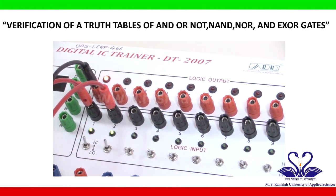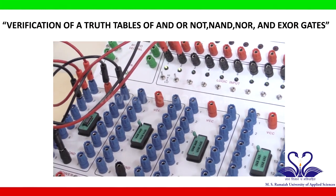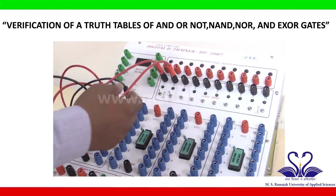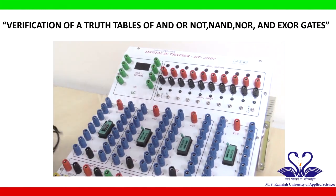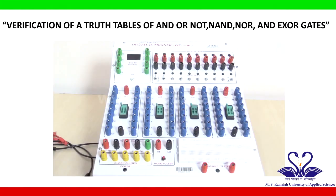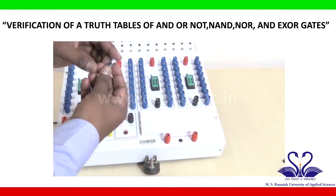Similarly, we will verify the OR gate. Before going for OR gate IC connection, turn off the trainer kit. Again remove all the wires. Remove this AND gate. This is IC number 7432, based on the circuit IC diagram, we will do the circuit connection. So let us take an OR gate. It is 7432. This is a 7432 IC.